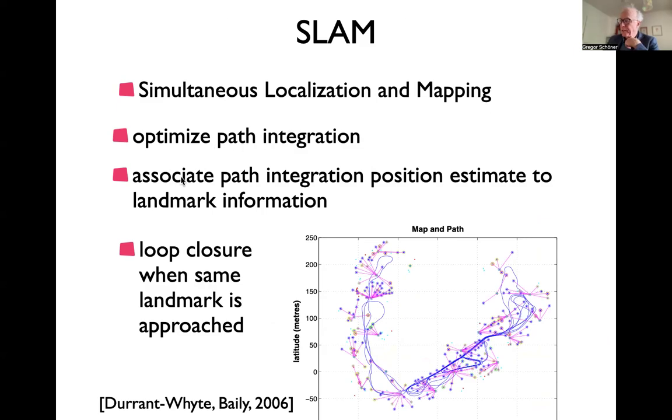And then you have some algorithm for determining when you are going to take the sensory information and put that down as landmark information. Typically you do that at some discrete points, and there are different ways to do it. For instance, based on there having been a significant change in the sensory information, or you just do it randomly in some sampling sense. And at those points, you store the sensory information that you have.